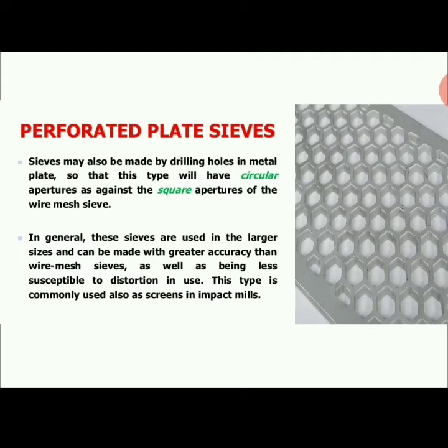This perforated plate possesses round holes. These round holes are mainly used for fibrous materials. Also, it possesses slots, like holes. These are used for amorphous and crystalline materials. Also, it possesses cross slots. These are also used for amorphous materials and slurries with coarse particles.